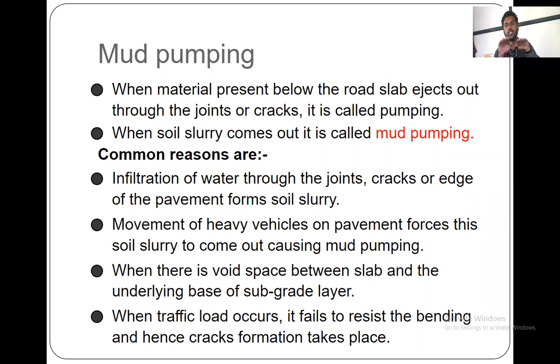Suppose this is the joint; the water will penetrate through this joint if proper sealant is not provided. If cracks are there, the water will enter through the crack into the soil, mix with it and form slurry. And suppose a heavy vehicle is passing over that joint. Due to the application of that heavy load, what will happen?